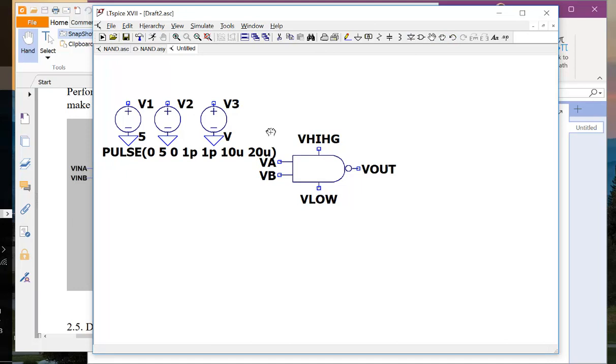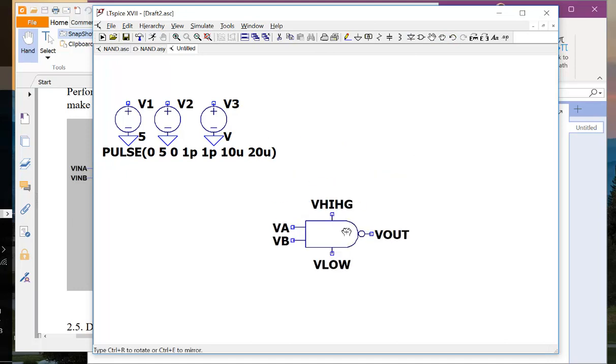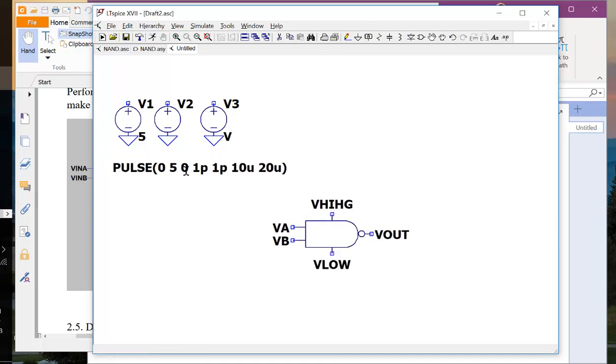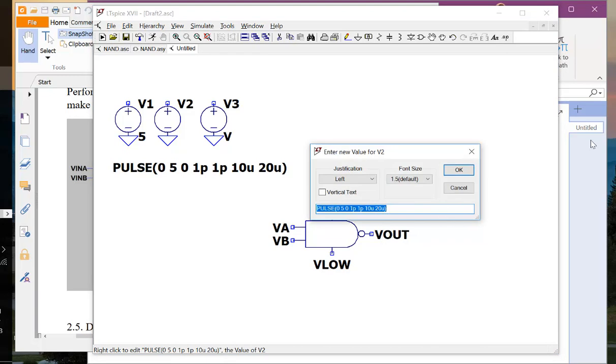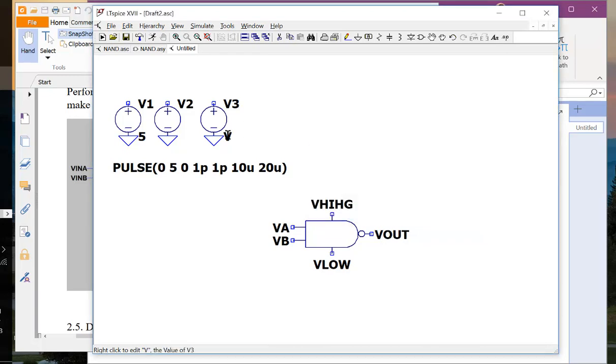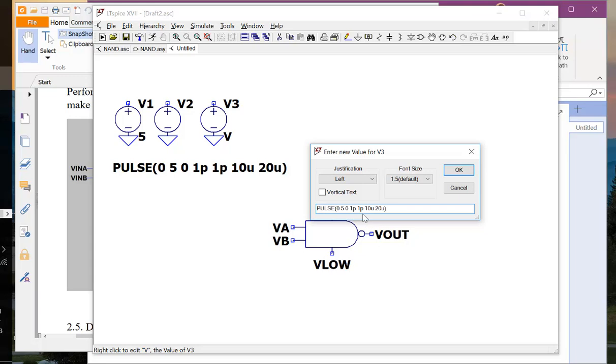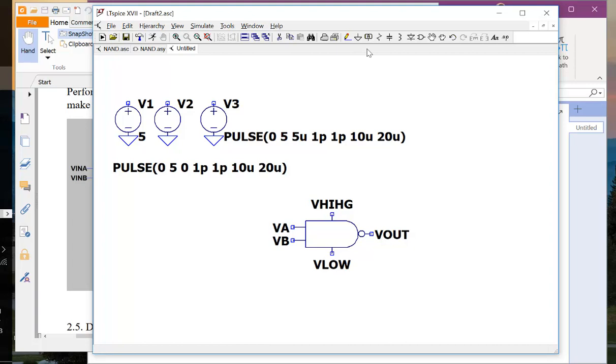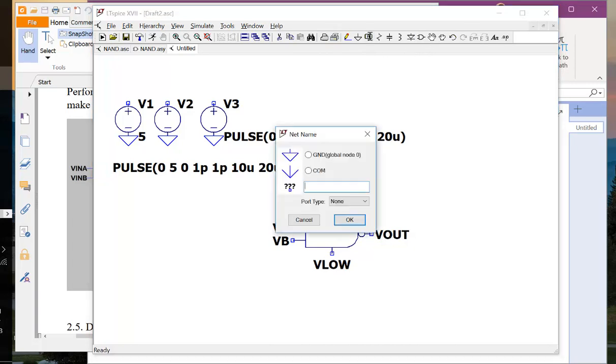All right, and now let's move this down a little bit. And now I can right-click this and copy, right? And right-click and paste. So now we just need to change the time delay here, otherwise if they're overlapping, you're not testing the signal combinations. Let's just make a little, like 5 microseconds of time delay, so you can explore all these different combinations of the inputs.